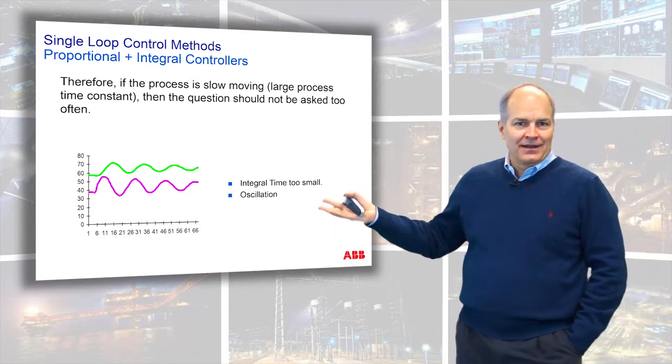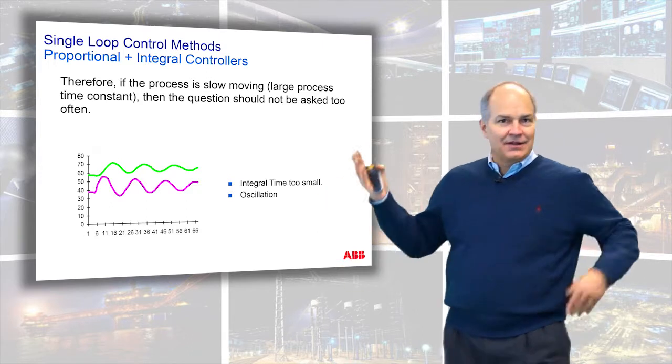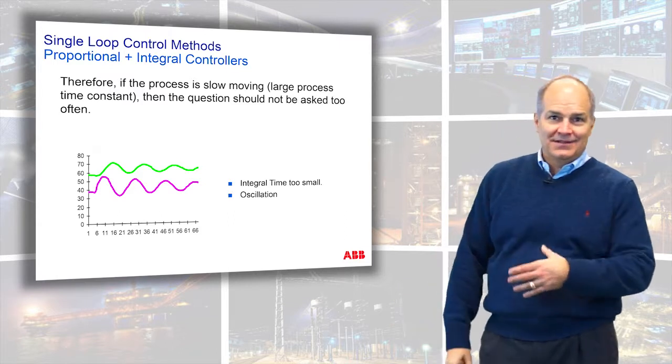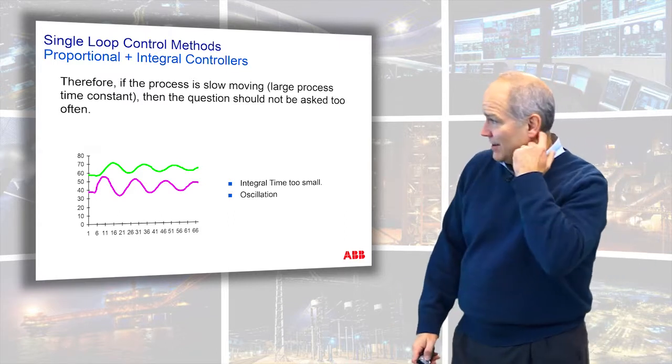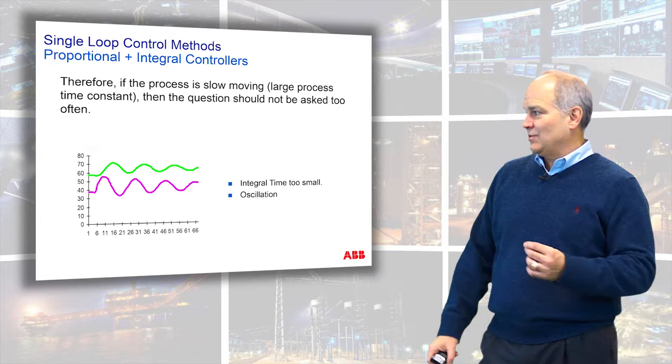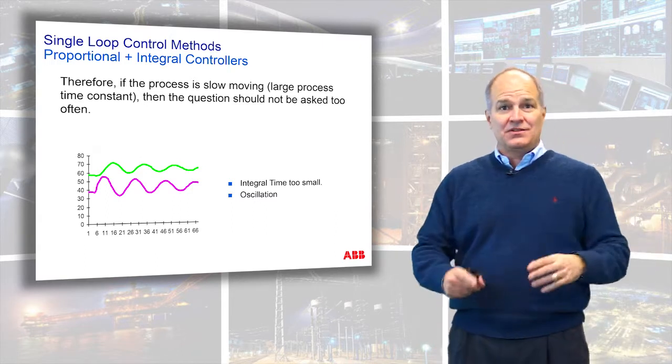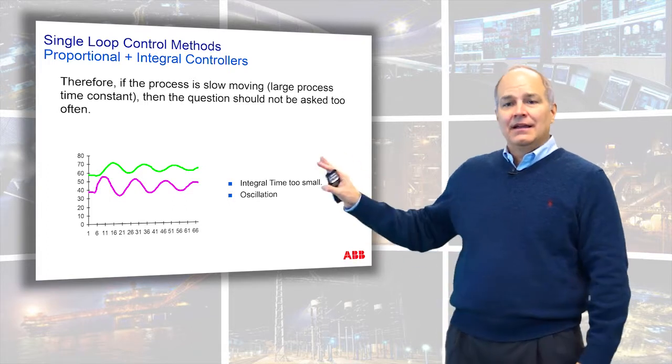So I call that ringing, and I can still remember someone said, "Well, I don't hear anything." And I go, "No, sorry, it's oscillating. It's just oscillating in an underdamped manner." But this isn't good. So this would say that your integral, you're resetting too fast, or your proportional gain is too high. Remember, they're related, and I'll talk about that.